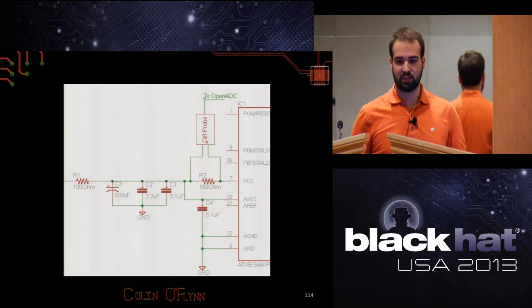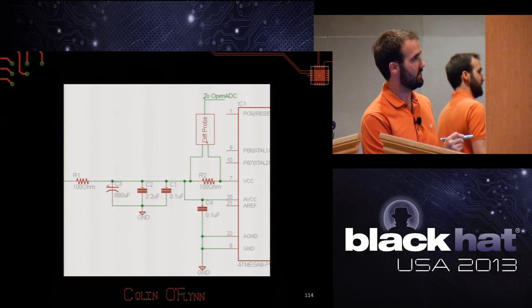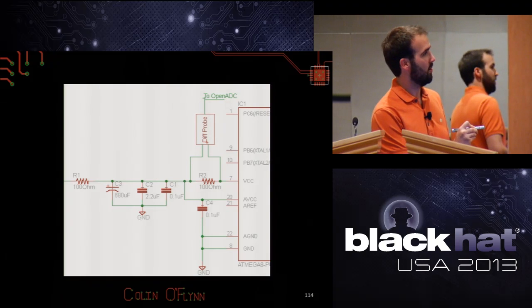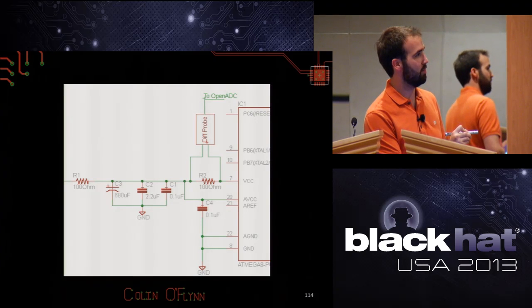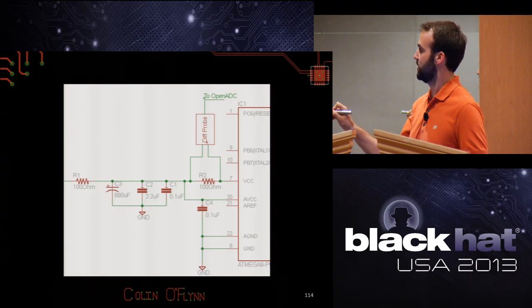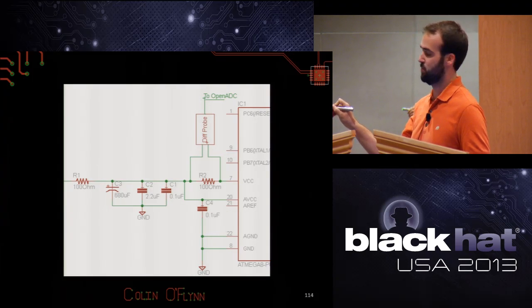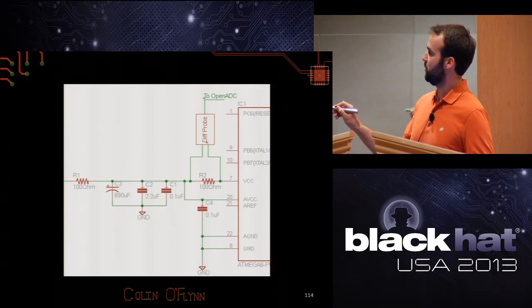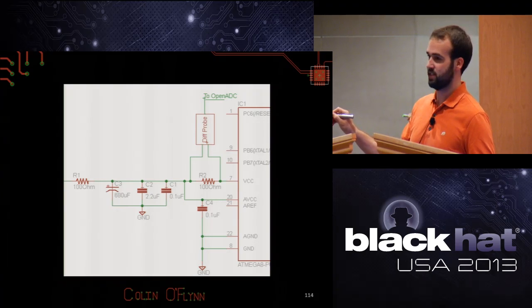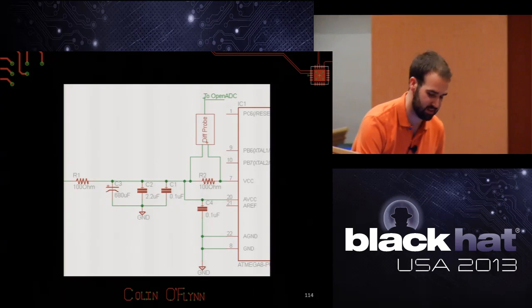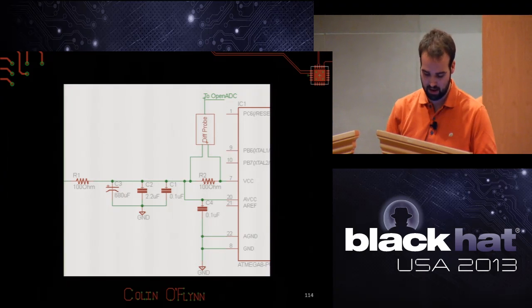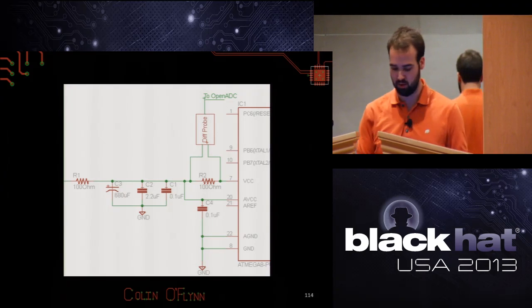So instead what we use is what's called a differential probe. All this does is you can see how there's a probe here and it's connected on each side of the resistor, that shunt I'm measuring with. The noise in the system tends to be coupled onto both sides of that resistor. So the noise coming through this line will more or less be coupled evenly to both sides. There's a tiny bit of variation, but we don't care. Now, this probe is only measuring the difference between the two sides of the resistor. So the noise that's common is irrelevant to the measurement then. So this is a really easy way to sort of obliterate that noise problem.